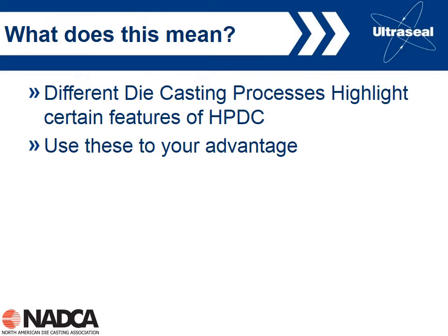This is basically going to save you a lot of heartache and probably some considerable cost too in terms of die changes and maybe some other issues. If you're concerned about pores in a heavy section casting, you should consider a high integrity casting process, squeeze casting or semi-solid casting, which helps to control the porosity in the casting. So don't just say this is going to be a very difficult die casting and then live with tool changes or live with high scrap rates or any other things that are going to add significant costs.